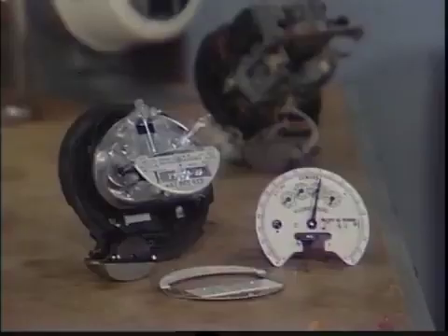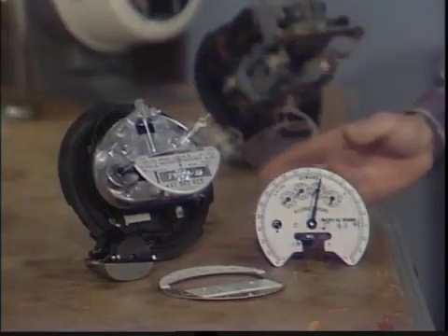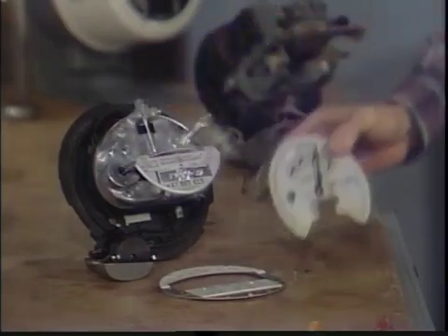Demand can be measured in kilovolt amperes, kilovars, amperes, or any other suitable electrical measure. But probably the most common demand measurement for billing is the kilowatt demand. Now, a kilowatt demand meter is typically a kilowatt-hour meter with a demand register added to it. The demand register can be mechanical, thermal, or electronic. Each of these 3 types of demand registers is associated with a method of responding to and measuring demand.